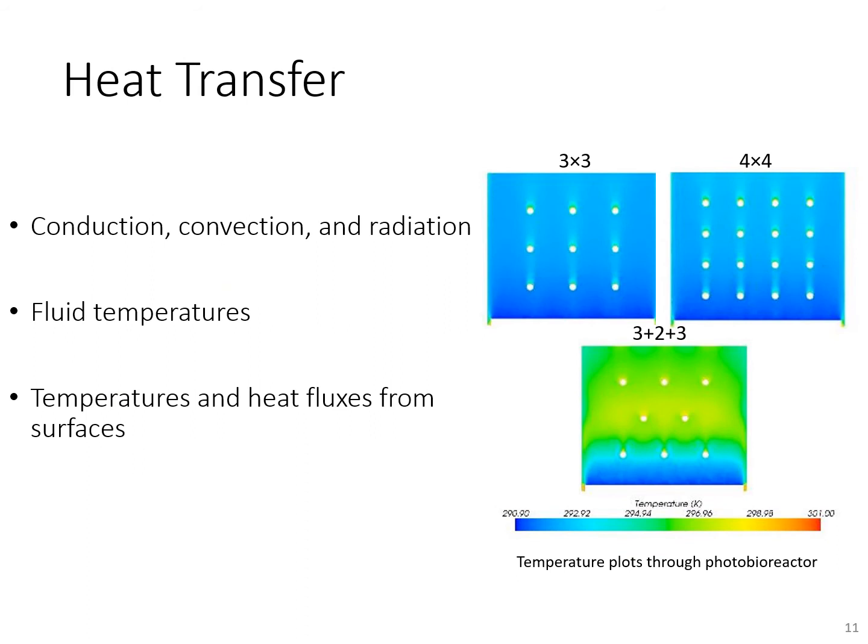CFD can also model temperature distributions due to heat loads or heat losses applied to a space or system. Phenomena captured by the CFD software can include all three types of heat transfer: conduction, convection, and radiation, depending on the parameters of the system. Additionally, temperature gain and loss within the system can be provided by either temperature difference of a fluid temperature coming into the system compared to the initial conditions, or by surfaces that might be providing a heat flux or temperature difference to the nearby fluid motion.